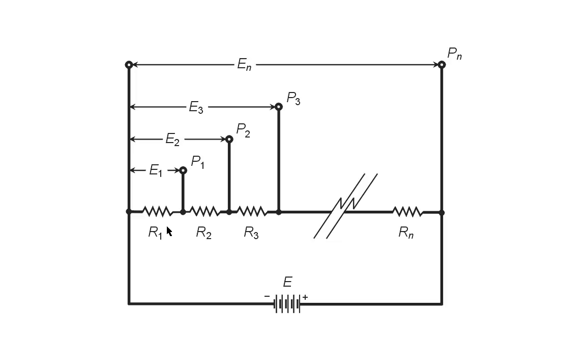The other problem that you need to watch out for is if you make these resistance values quite low, you're going to have to make certain that you make the resistors robust enough so that they can withstand the power that they're going to be called upon to dissipate. In this case, for example, we have 9.0 ohms and a current of 0.5 amperes.